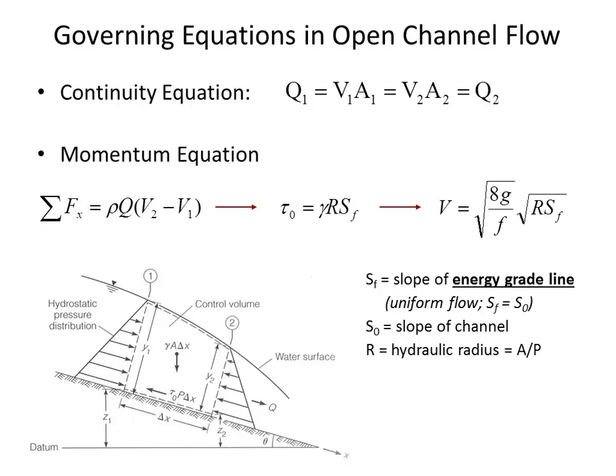You'd naturally think, well, if you put a step in the channel, it's going to get deeper. And sometimes it gets shallower, actually, after it flows over an obstruction. So it behaves in unexpected ways, and you really have to do the calculations to be able to predict whether it's going to get deeper or shallower in any of those cases.